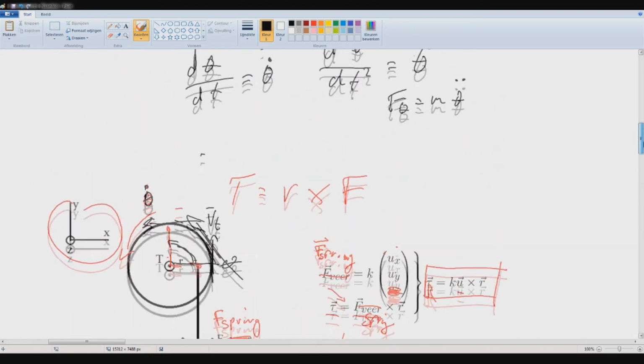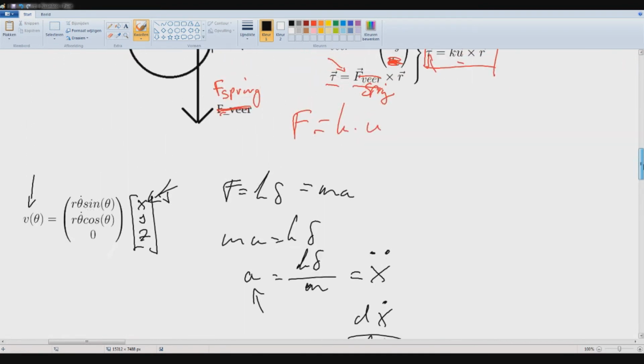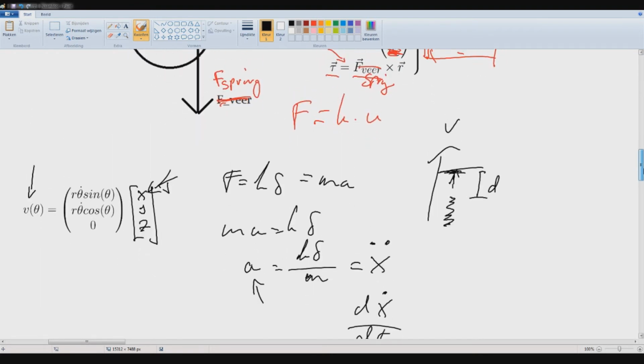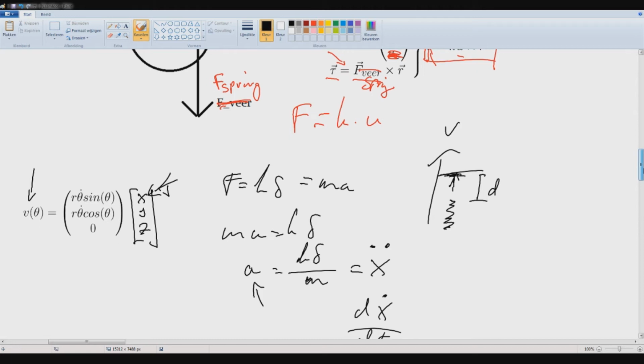Otherwise, what will happen if that's not the case is, if the motor, for example, is a lot faster than the spring, we have a spring in energized state and the motor is around here. Therefore there is this distance that the spring will not deliver a force to the frame, and therefore it will just go instantaneously. It doesn't deliver a force to anything, so nothing happens and you won't leave the ground. And we do not want that.